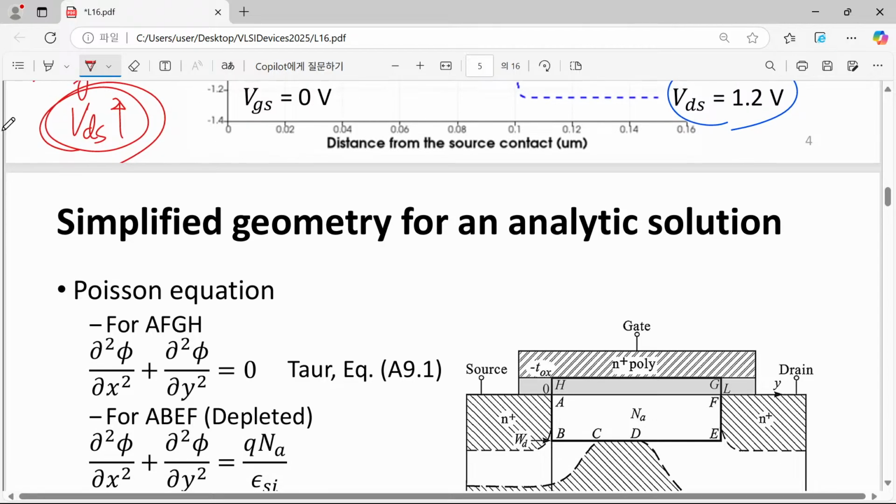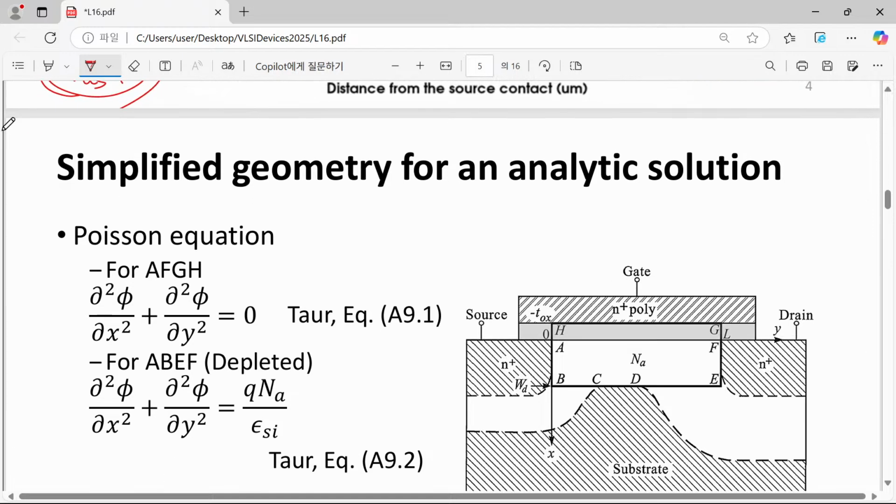So the remaining lecture in today's session is devoted to some simplified analytic expression for estimating this phenomenon. So dependence on length scale and drain voltage, both of them are considered in this simple analysis. Of course, I'm not saying that this is perfect and exact, but this provides us a good estimation about how you can understand their functional dependence on threshold voltage.